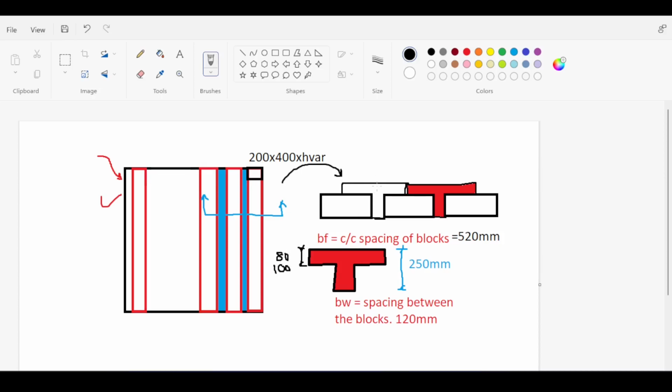Now, this topping slab is part of the ribbed beam, yes, but it also contains a steel mesh that is just laid in both directions, in this direction and in the perpendicular direction, but I'm running out of space. This steel is calculated based on the minimum steel of a slab that has a height of 100 millimeter or 80 millimeters, so you can calculate this via your code. This steel mesh is not part of what I want to design because this is just minimum steel. What I want to design and model is the rib itself. This is just called a topping slab, and I'll have a little hack to model it later.